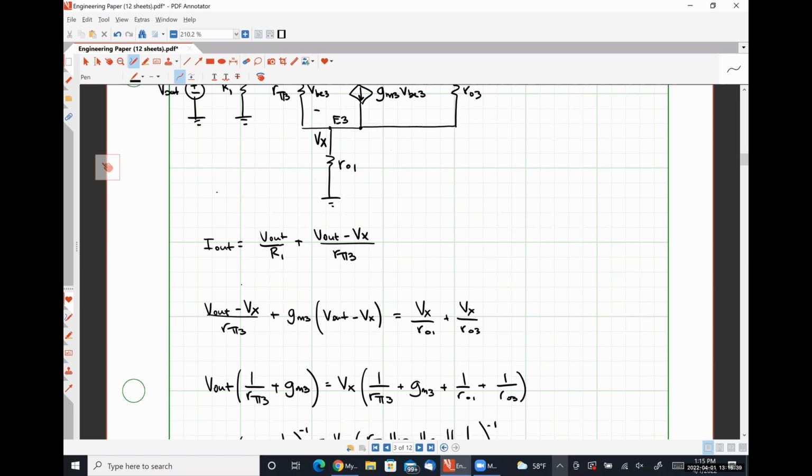Yeah, because it says the cascode is effectively supposed to behave like a common emitter amplifier, which definitely has a negative gain, but with a really large output resistance. That is its absolute function. So the cascode gain equation should wind up with negative gain. So I apologize for missing that.